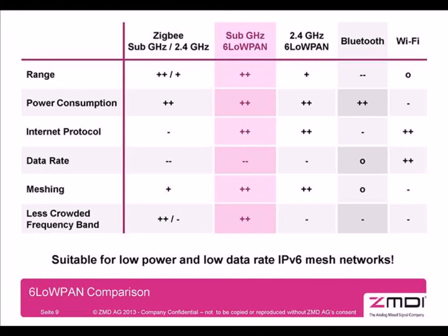Okay, let's continue with our module, with the hardware. Our module supports the European frequencies and the North American frequencies. In Europe, we support 4 channels, and the data rate is 20 kilobits per second in the BPSK mode, or 100 kilobits per second in the QPSK mode. The output power is 5 dBm, and the sensitivity is -110.